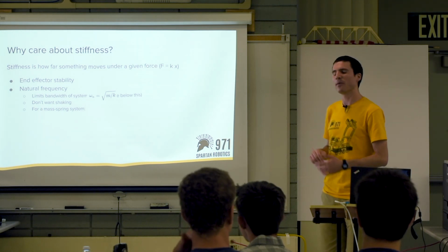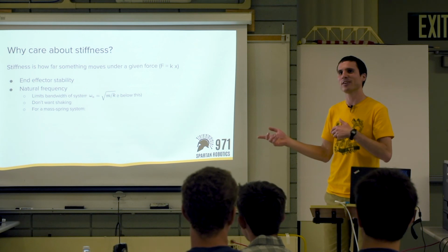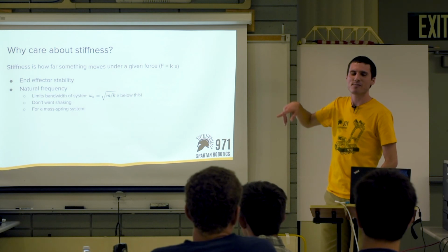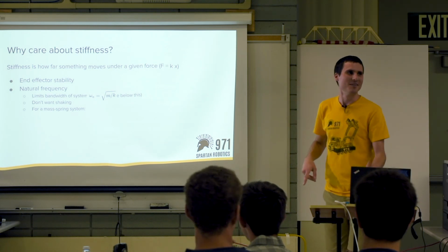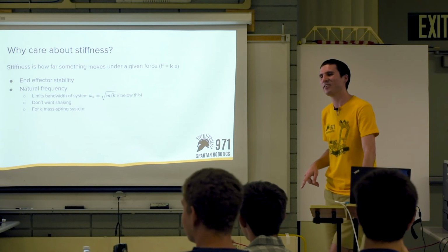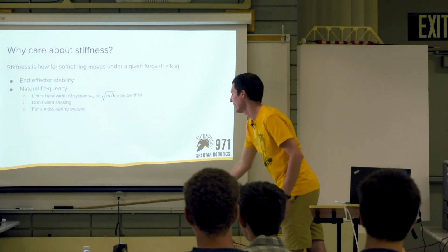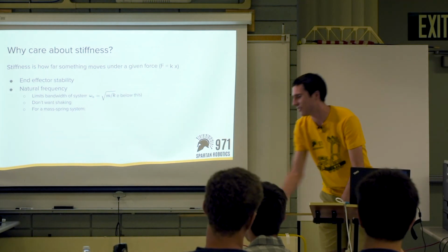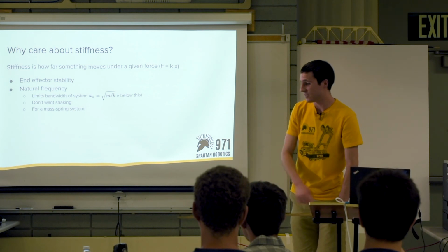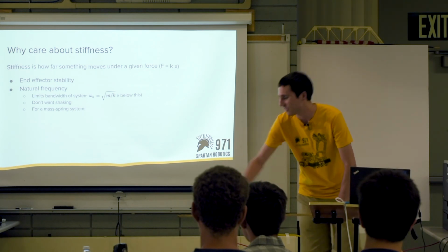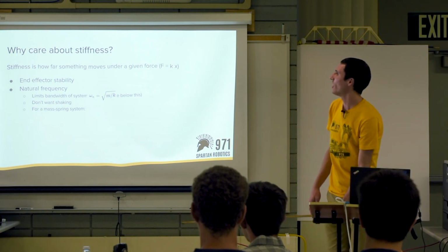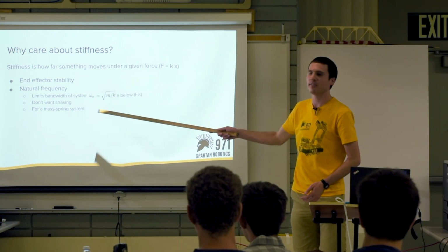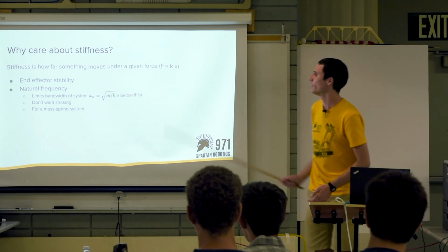With a mass on a spring, if you shake the spring, you know how it vibrates at a certain frequency? If we take this yardstick and mount it solidly, we twang it, and you see how it vibrates? This is based on the stiffness in our system, and it's also based on the mass of this thing and how stiff it is. It turns out that frequency is related to the square root of stiffness over mass.